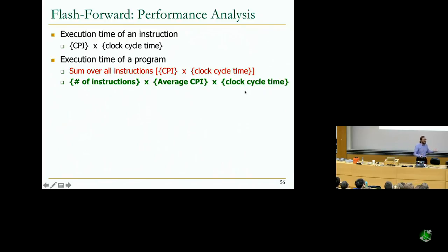Now, it becomes an art and a science at the same time. How do you get the highest performance? By making this multi-dimensional trade-off, right? So ISA design clearly affects this. ISA design implicitly also affects this. Microarchitecture design affects both of these. It cannot affect the number of instructions, right? Microarchitecture is already given the instructions. It can do stuff to those instructions to execute them fast. Fast meaning cycles per instruction and clock cycle time, minimize both, but it cannot change the number of instructions. Whereas ISA design affects all of them, although this one it has an indirect effect on.